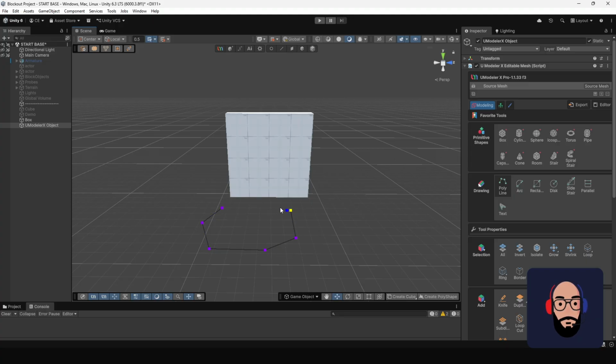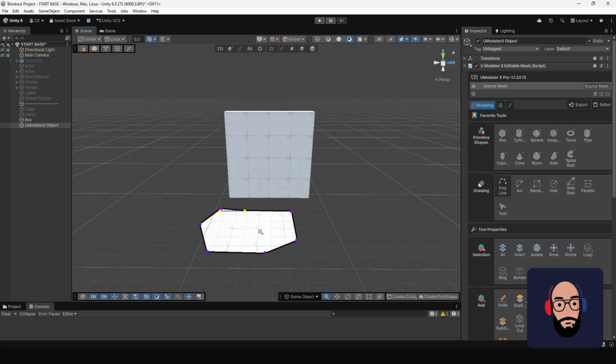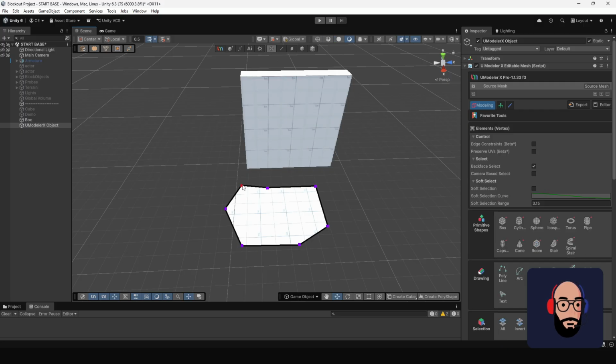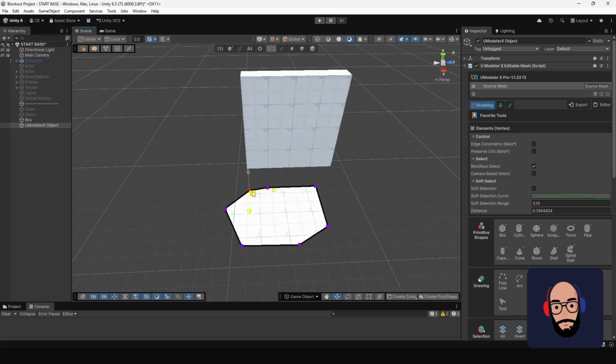This is useful for many purposes, but one of the most common ones is creating a shape directly from the polyline. When you're finished, press Escape. From there, you can manipulate the shape just like any other object. Move points, select faces, extrude upward, inward, start forming unique geometry.